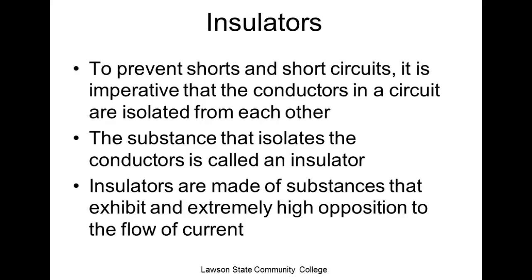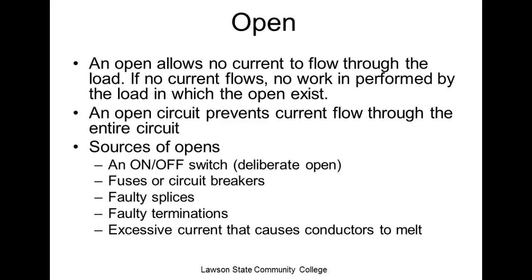Except when it comes to the point where you have to splice them or do what? Terminate them. And of course, you have to be real careful when you terminate, because if you leave too much exposed wire, then you could get what? Short circuits very easy. Very easy. Or if you don't cut off enough insulation, and you get the insulation up under the screw, you might not create a good connection. Opens. An open.